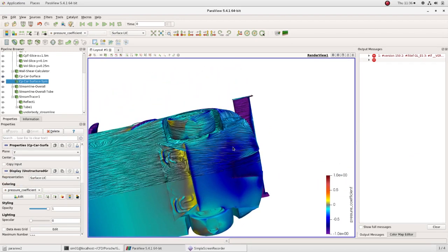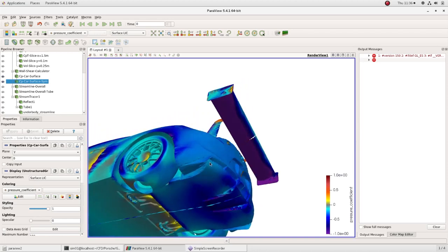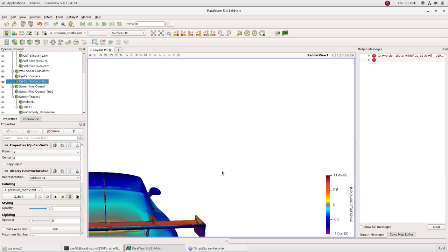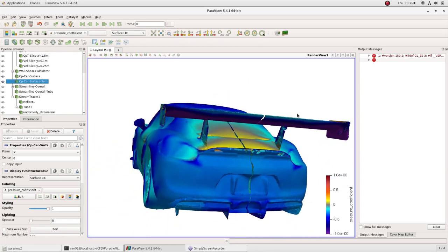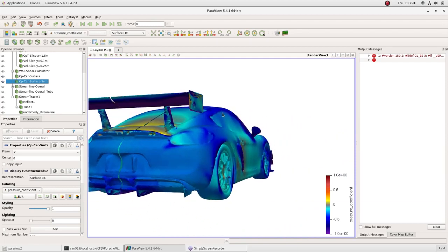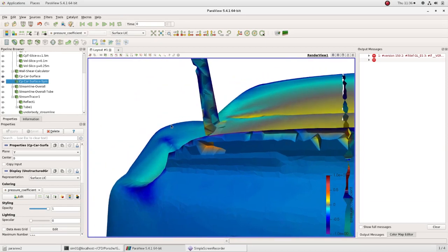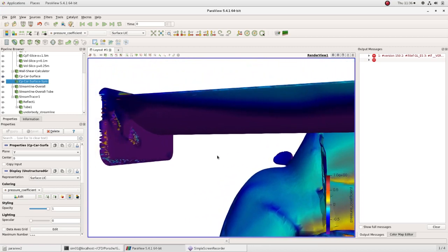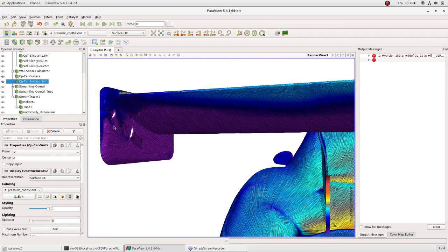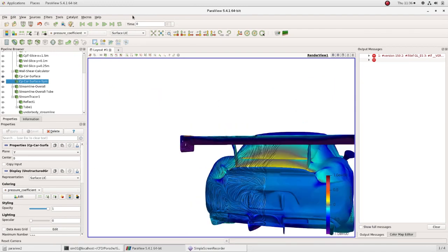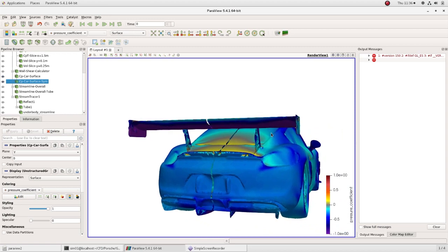We have also used these plots to correlate our rear wing to real-world testing of FlowViz, as well as various other components on the 987. Correlating our CFD to real-world results ensures we are analyzing components accurately, our meshing quality is appropriate, and ultimately the results from CFD are accurate as well.